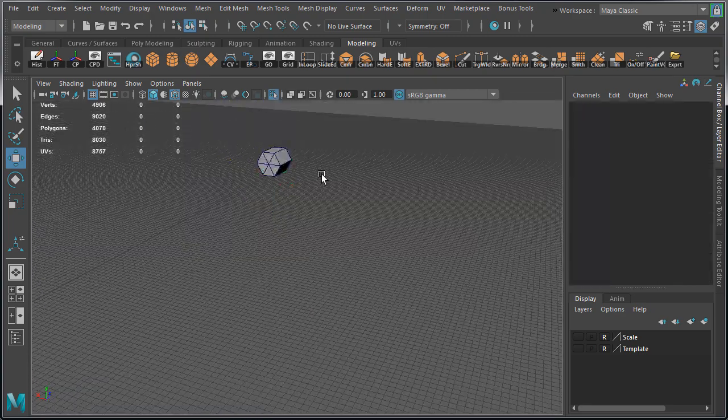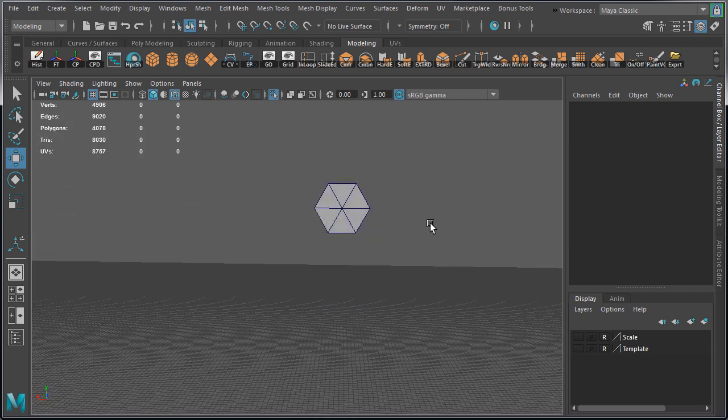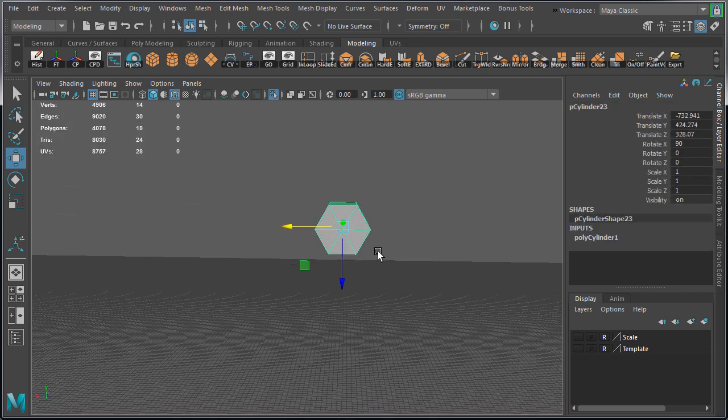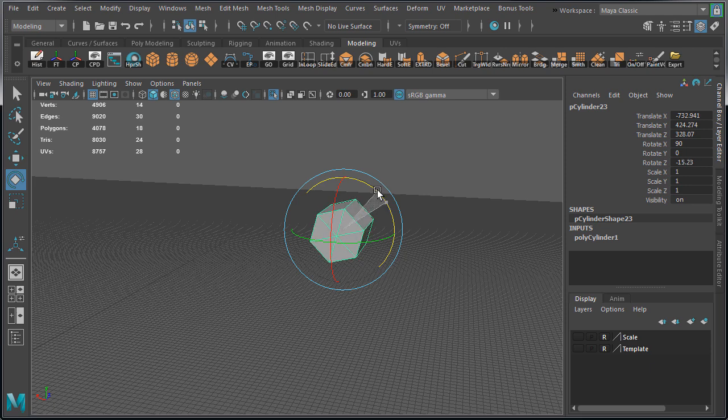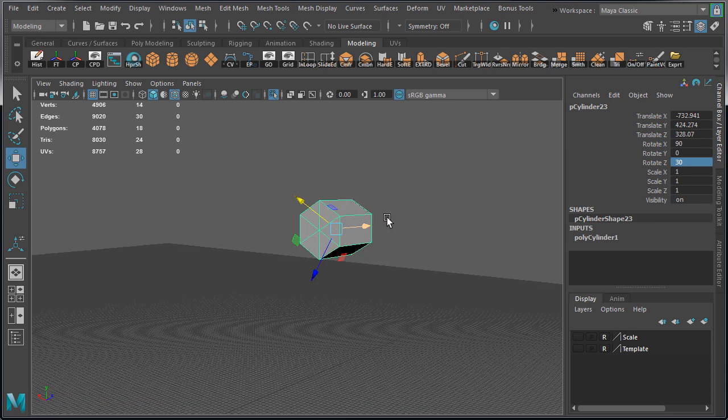Let's go ahead and rotate this on Z 30 degrees, because I don't want to have a flat plane at the top of this wire, but rather this corner edge. Since our wires are going to be very low poly, I want to help the shading of the cylindrical object to appear more round. So by moving that edge so it's pointing to the top, it just looks better. But actually in the end it doesn't really matter because our wires are going to be so small that the player is not going to see them up close.